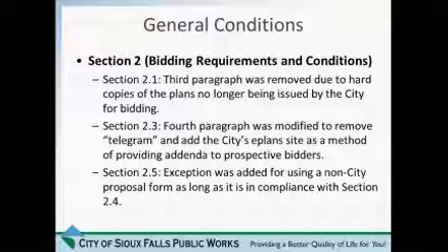But the intent behind that is, when we're putting the plans together, let's say there happens to be a mistake or a bust in the pipe quantity, and nobody catches it, but this contractor who's bidding on it catches it and says, "Oh wow, they really underestimated the amount of rock excavation or pipe that's needed." A normal price might be, say, $50 a foot. And they say, well, I'm going to bid everything else really low, but then I'm going to bid $200 a foot for that particular item, knowing that it's going to overrun. So then I'm going to get a whole bunch of extra payment.